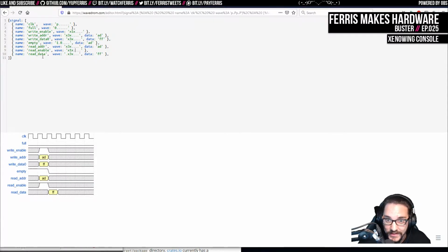What should actually happen is this empty signal, instead of going low there, should go low as a consequence of the fact that we're writing to an empty FIFO. So within that same cycle, this should reflect that it's getting incoming data, and that the write's actually okay. So the fact that we're issuing a write while the FIFO is empty should actually work. And as you can see, the read gets done a cycle earlier, by virtue of the way that the memories work.